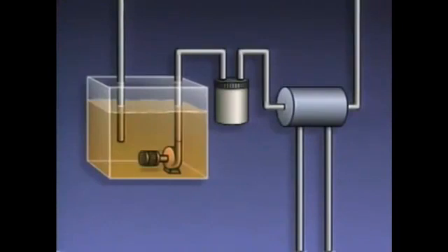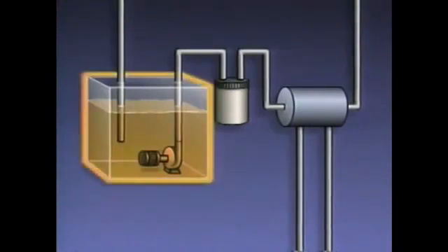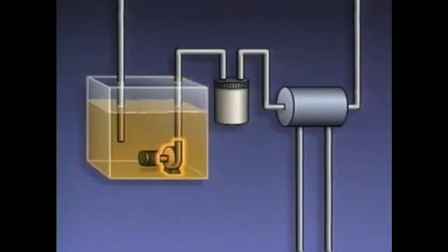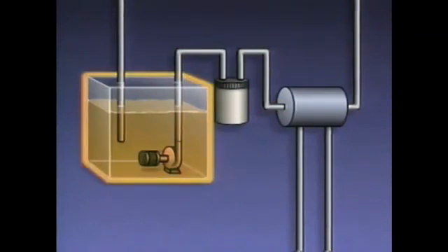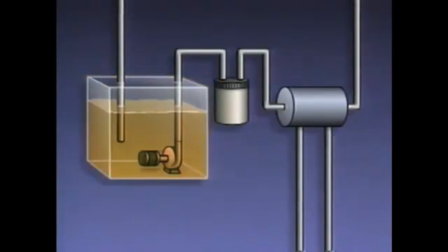The function of a compressor lubrication system is to provide the compressor with a continuous supply of clean oil at the proper temperature. This is a simplified illustration of a compressor lubrication system. The system includes an oil reservoir, an oil pump, an oil filter, an oil cooler, and oil lines. Oil for the lubrication system is stored in the reservoir. During operation, the pump draws oil out of the reservoir and moves it through the rest of the system.